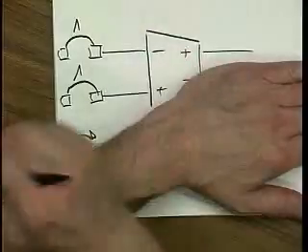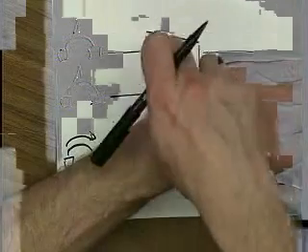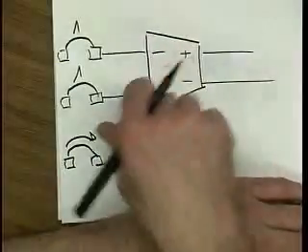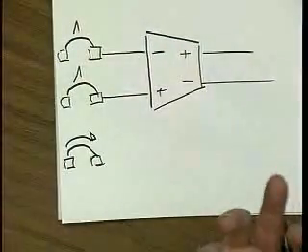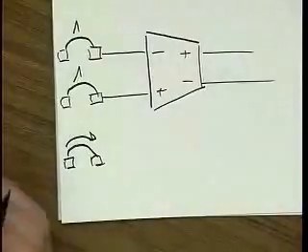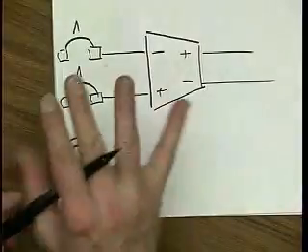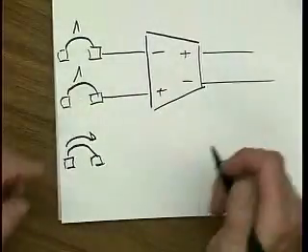Most of the noise comes from the diff pair, from the input transistors anyways. I again refer you to the homework, problem 1. Okay? And consequently, adding the extra output adds no or marginally additional noise, right? So the noise is about the same. But let's look at the signal.